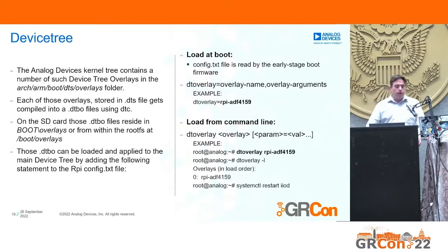So in our Analog Devices Linux kernel tree, which is nothing special, we have a bunch of extra files in there that are not upstream. They are device tree overlays, for example. We create them just for internal testing and also for customers who just want to test something without actually writing something. And those are located in arch/arm/boot/dts/overlays.